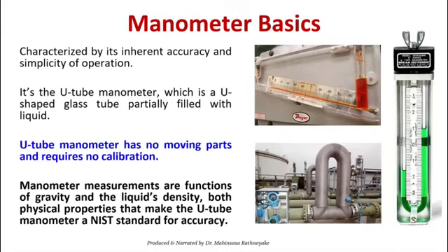If I tell you as facts, if you get the U-tube manometer, you can see a picture here. You can see where U-tube manometers have been used in the industry to measure the pressure, right? There also you measure the difference of pressure, or differential pressure, between the 2 points, the 2 flanges before and after the U-tube, and then the height difference is measured. Even nowadays you can fix a control circuit, measure the height and convert it into an electrical signal. Then you can electronically obtain the reading, right? And also you can control. So that is the importance of U-tube manometers.